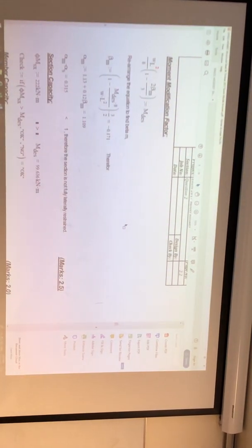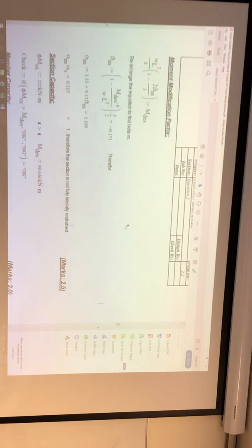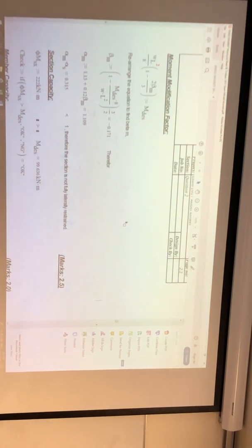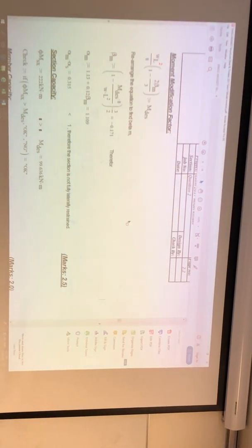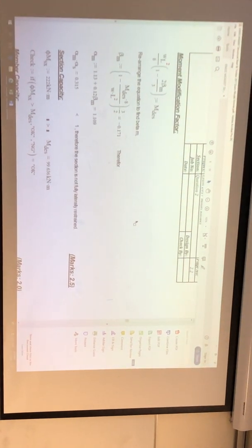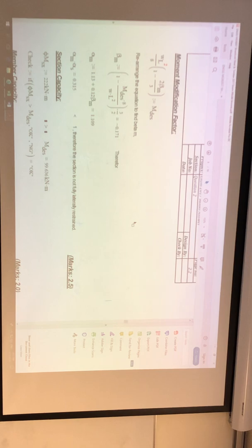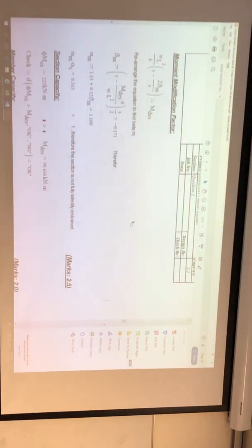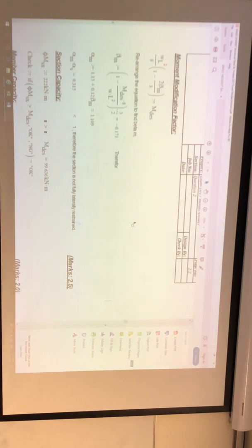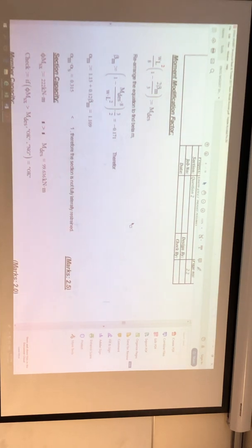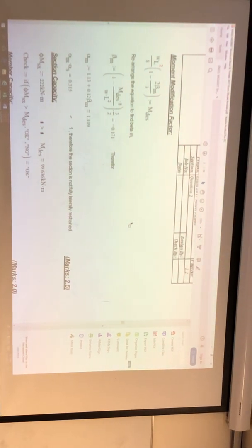So let's say you got a beam, right? The first quarter point is here. So I split the beam there, put a joint there. There is a node now. So this is a separate member, this is a separate member, in terms of just giving me values. Then this member I'll further divide into 4. So then the moment diagram, let's say it looks like this, it will give you a value here, value here, value here, value here. And you just pick it from there. Easy as. Right? You can do that in Multiframe.